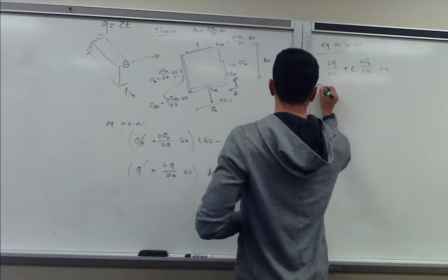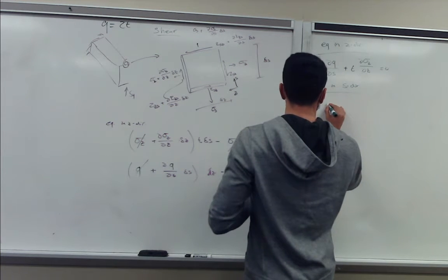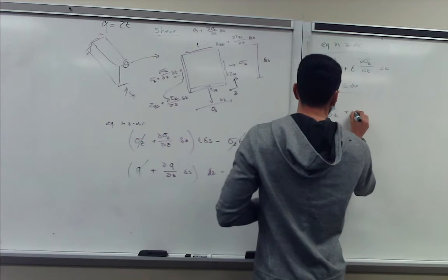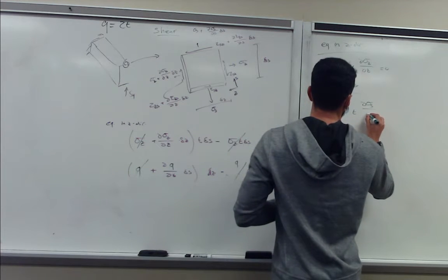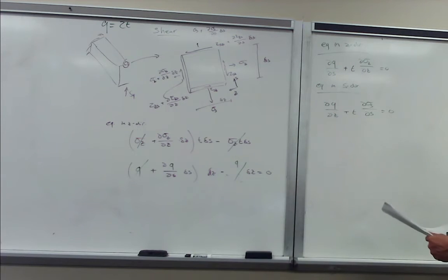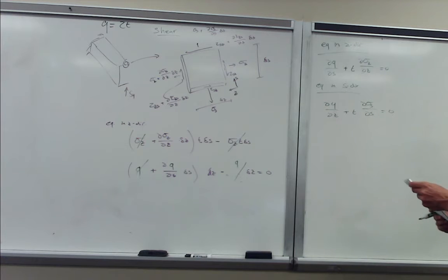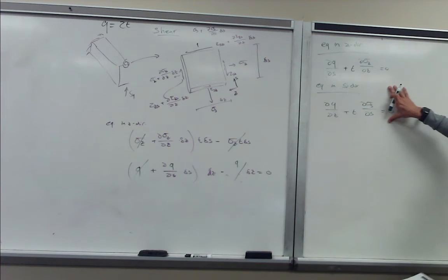And then if we do our equilibrium in the s direction, what we get is dq dz plus t times d sigma ds is equal to 0. So we get two equilibrium equations. We're going to continue with just focusing on the z direction. This is just for completeness.